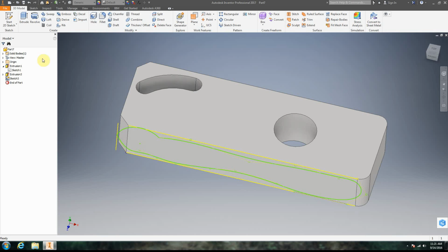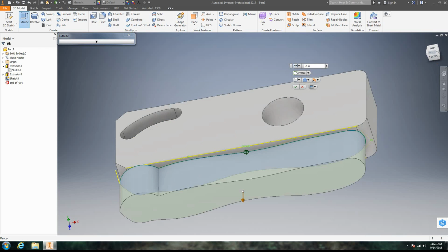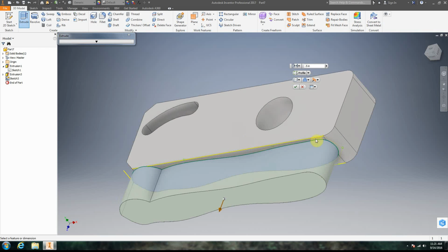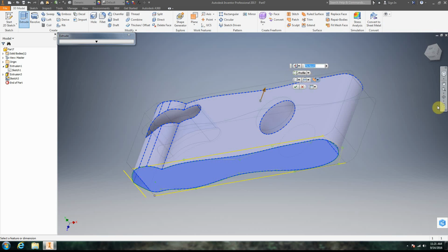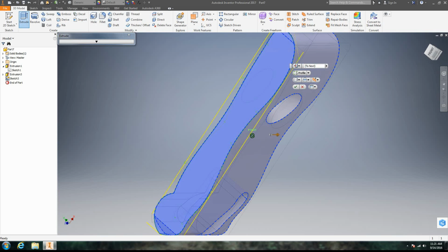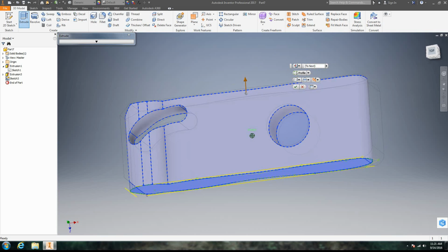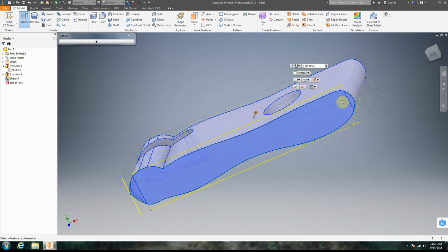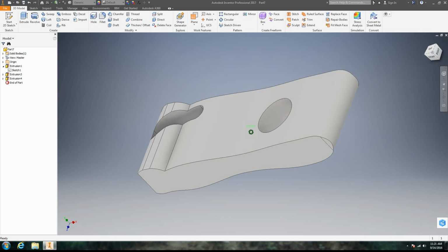Now I have this shape right here, and I'm going to go extrude. Notice how I get the extrusion. It selects the only available shape on the only available sketch. I'm going to do intersection, and then go to next face or body. Now notice what happens. It gives me this preview. So intersection, while cut takes away material and extrude creates material, intersection only leaves the material where two different extrusions intersect.